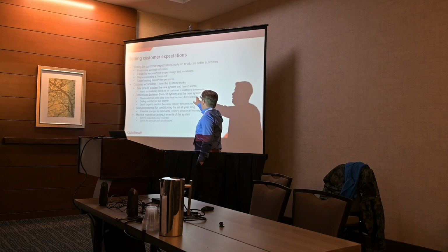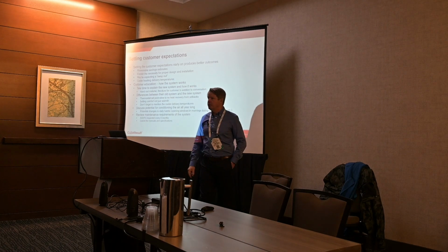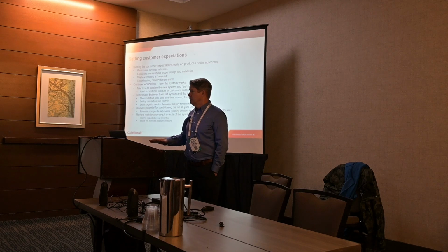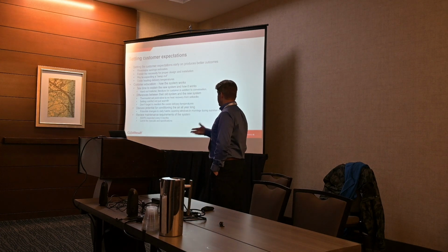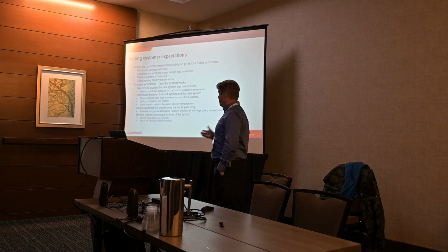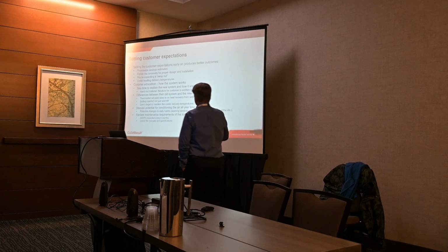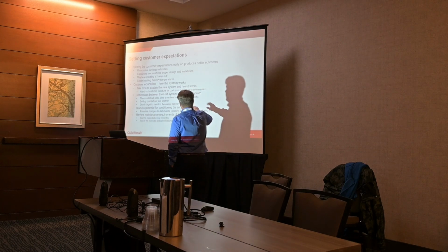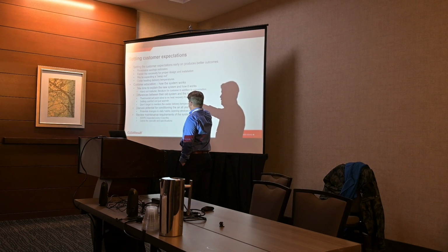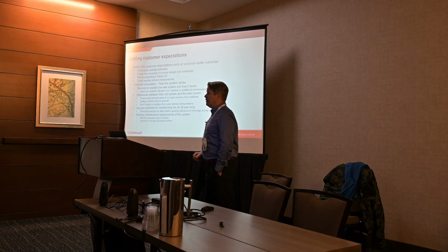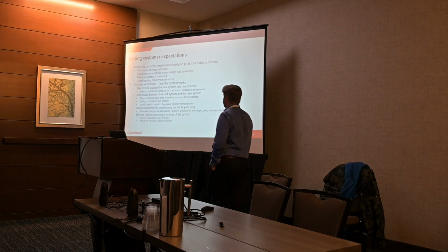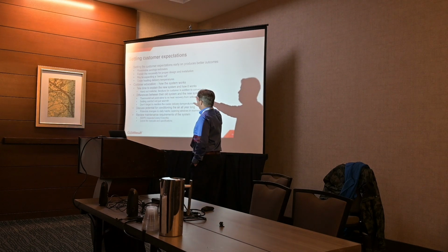Heat pumps don't recover very well from temperature setbacks. Okay, that's one of the things about them. You get a furnace blowing 130-degree air, and you can recover in an hour and a half, something like that. Heat pumps are blowing 100-degree or 95-degree air into a space that's 10 degrees cooler than it needs to be, and it's cold outside. It's going to take a while to catch up. So typically we don't set back heat pumps.